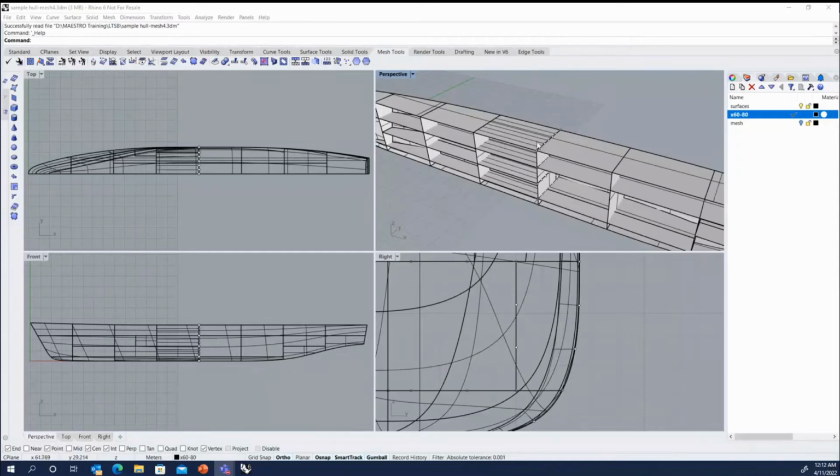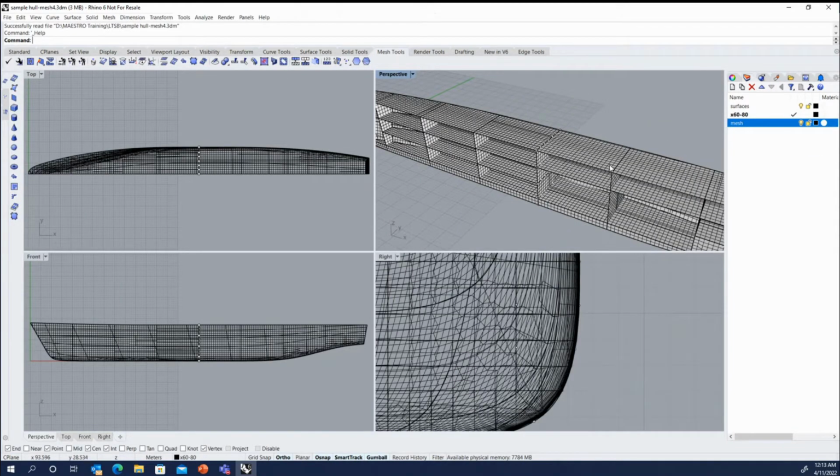We'll try and do initially just the strake-based model, and then we'll go on to do the regular model, the level 2 model, where we model all the individual beams. And the mesh that we're going to target will be approximately a 1 meter by 1 meter mesh, and that's roughly the density of the mesh that we'll be generating.